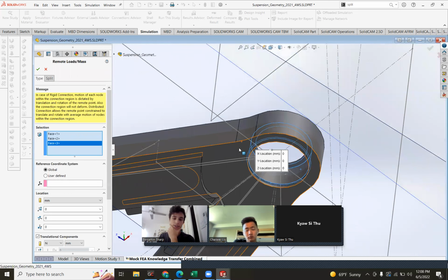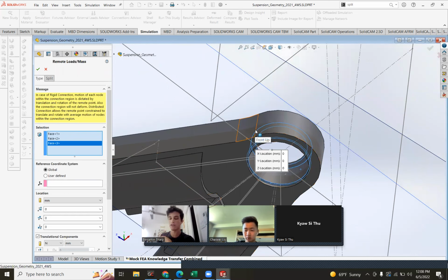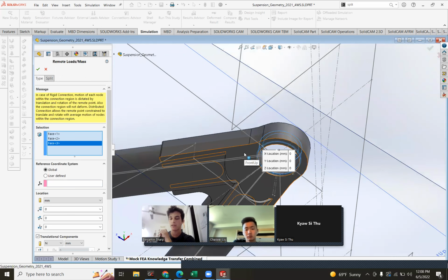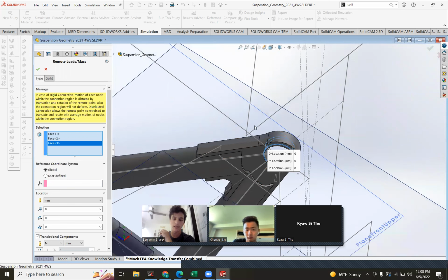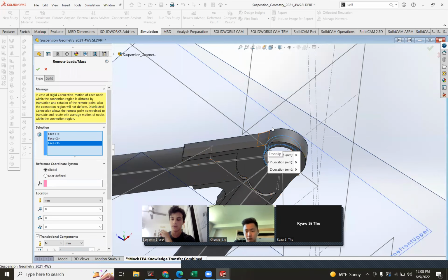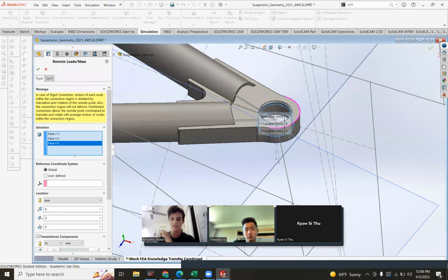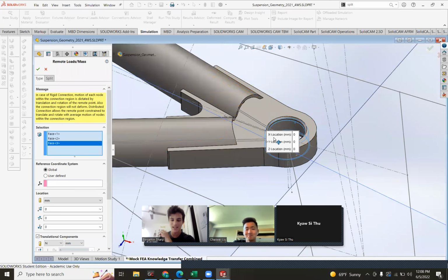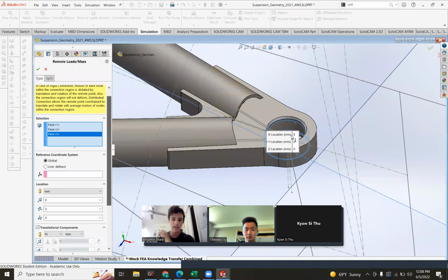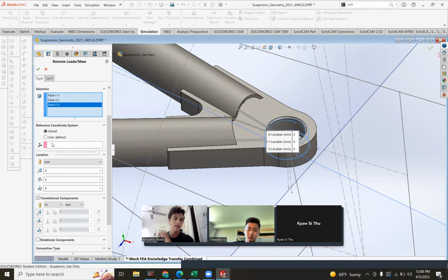Really nowhere else. You could maybe say some of the load is being experienced by the bottom of the wafer, but if you do that, it's probably going to tell you your design is way safer than it actually is, way stronger, because this is a lot of surface area with strong welded metal behind it. And in reality, we're not actually that fortunate. It's all being eaten up by the wafer on the end in the bearing cup. So that's where the load's being applied.